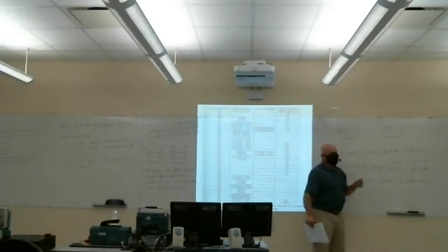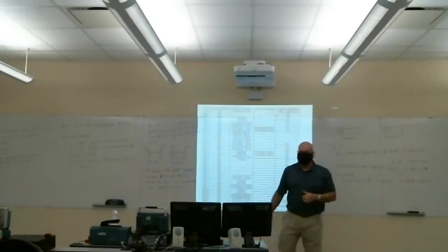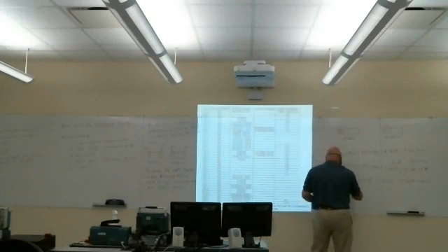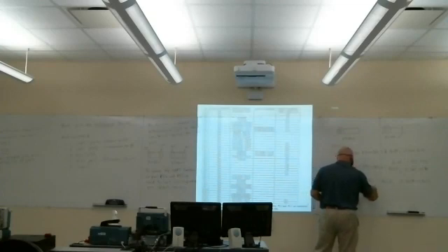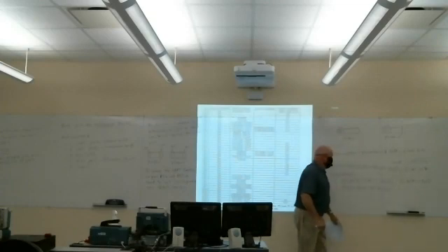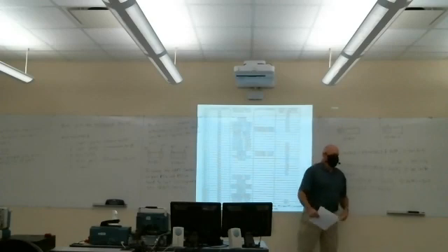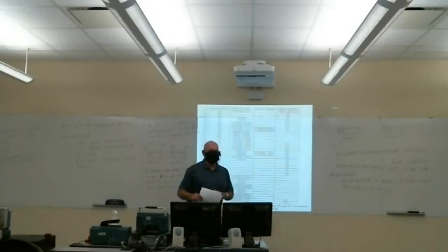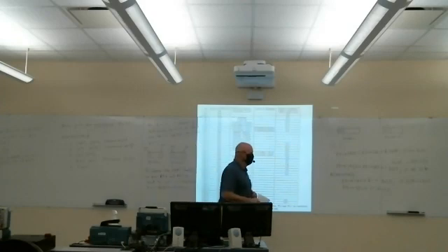I can think about only the 2 bits I'm interested in. And similarly, the other one, OR equal 0xC0. That's the other reason. I see the same 2 values here, so I can be pretty sure that I'm affecting the same 2 bits.